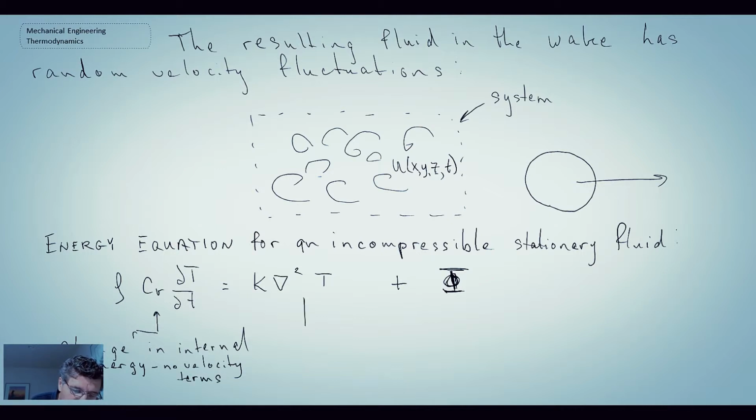The second term that we have here is thermal conduction. If you remember a couple of classes ago we talked about forms of heat transfer. We had Fourier's law there. This is a similar representation, although it's from the heat diffusion equation, but it would represent thermal conduction within the fluid. And the thing to note there, again, there are no velocity terms. So velocity does not appear anywhere in either the first or the second term.